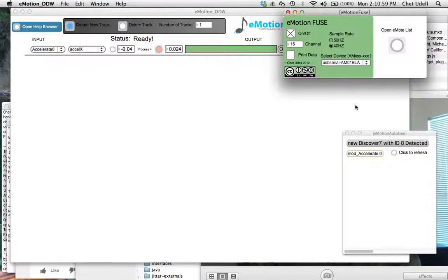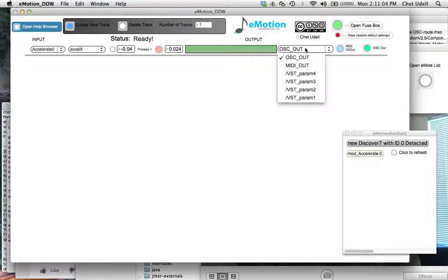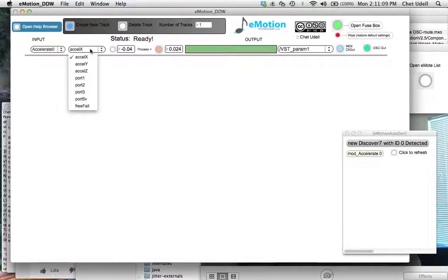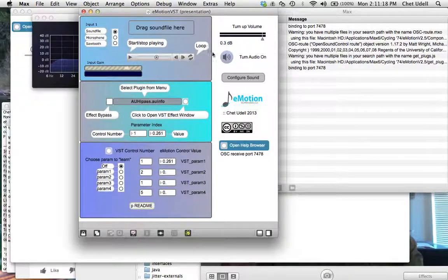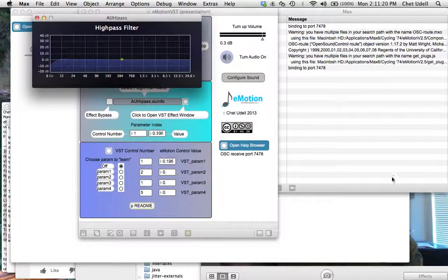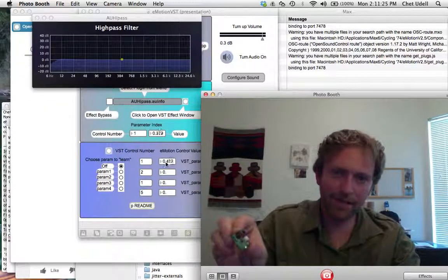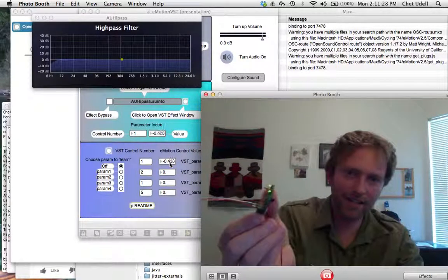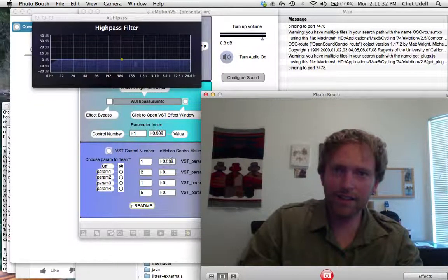So here you should have already started up your accelerate, your fuse is on, and everything's calibrated. Last thing is go to VST. Let's do param 1, and I'll do this one at a time. I'll set accelerometer X, and then I'm just going to go ahead and turn this on, and I want you to notice something. Something screwy is going on around here, which is, notice how I'm tilting it from side to side, and nothing's really happening. Well, take a look. I'm getting data values from +1 to -1. And remember, the sweep wanted you to give the data values in hertz.